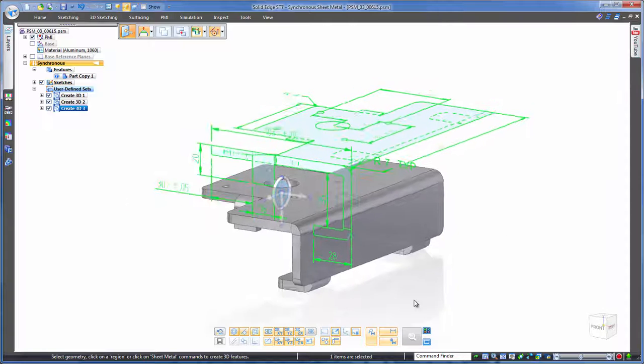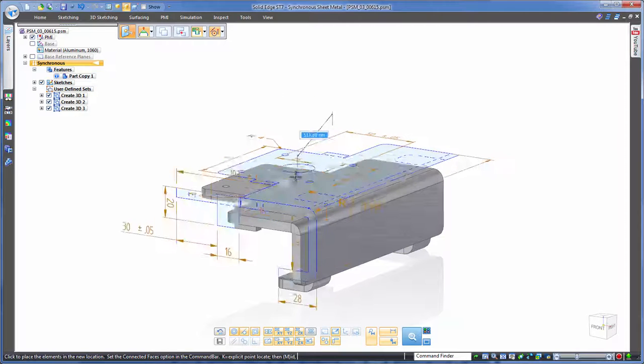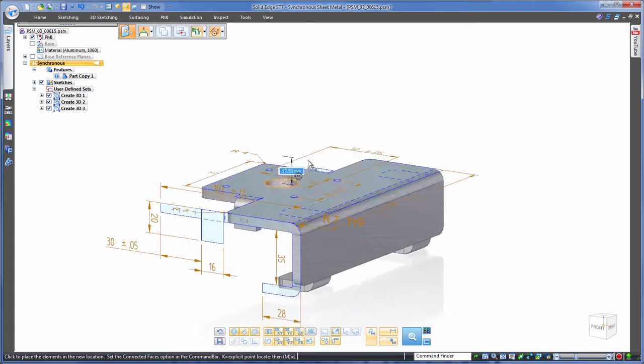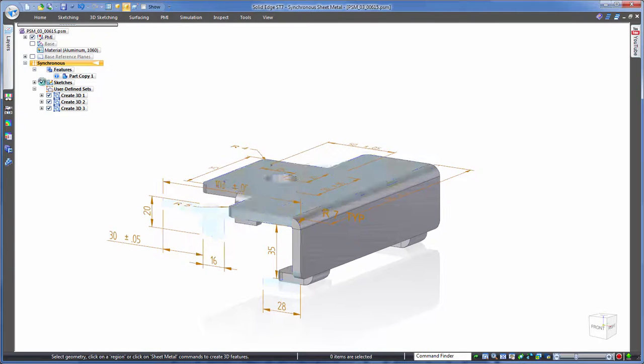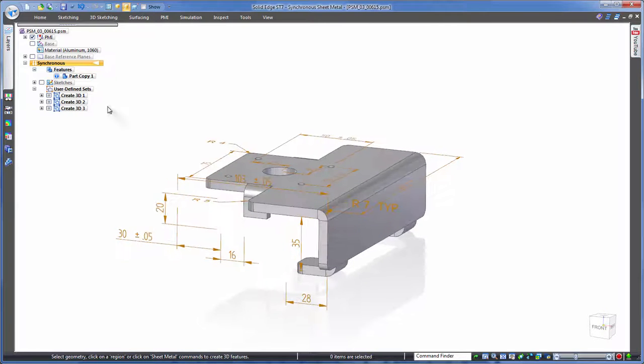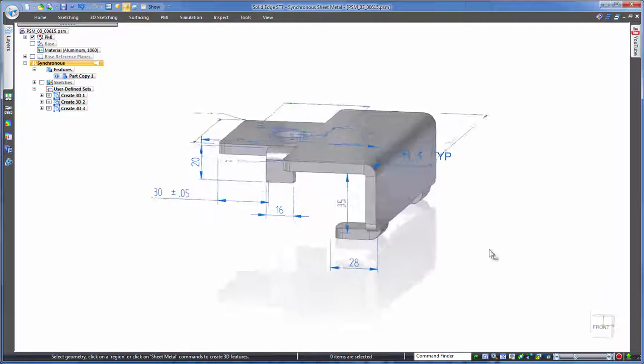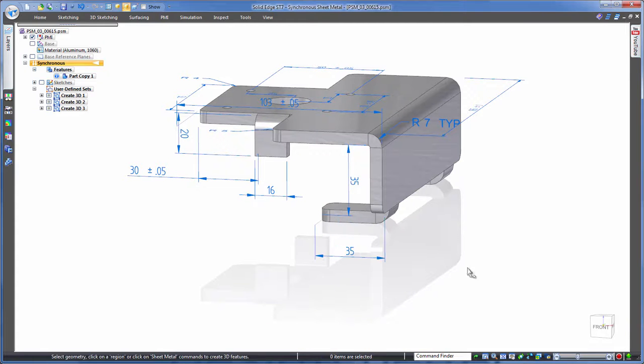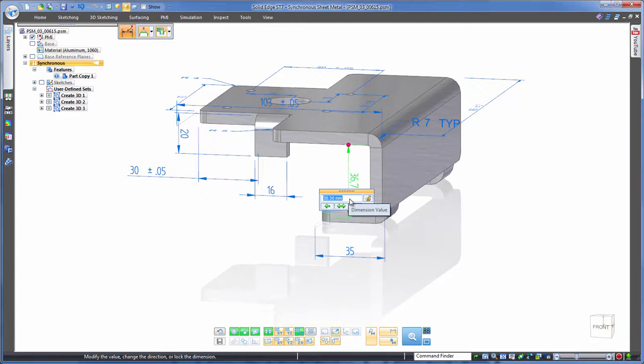Now you've already seen this steering wheel in action editing 3D geometry, and to keep things consistent, it can also be used for things like this, snapping drawing views into position over the model. So, nice to see the manufacturing intent overlaid in 3D, but wouldn't it be useful if we could control the model with these dimensions? Well, synchronous technology in Solid Edge can do just that. A simple click to attach, and these dimensions are now live, enabling us to make the required changes that we need whilst maintaining this manufacturing intent.